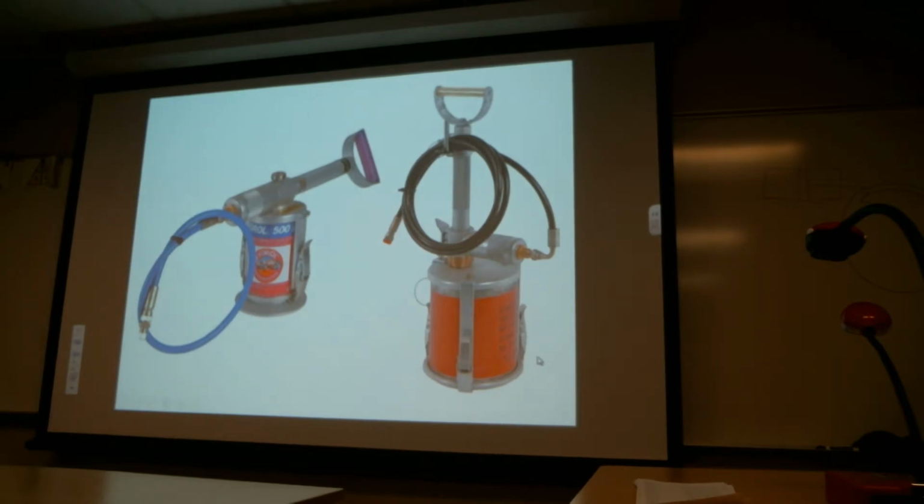This is what they use in the field for servicing reservoirs sometimes. They use self-contained units that have integral pumps, where the intent is really to minimize contamination that gets into the reservoir. The servicing unit uses the container itself as a method for holding the fluid that you're servicing with. Some of them have an integral pump, most of them do. This is an old military unit, but again, you can see it uses a gallon container of hydraulic fluid. This one is a commercial one. Again, it holds a quart container of phosphate ester-based fluid.